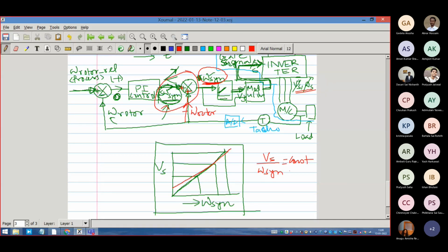So what will it do? It will integrate for more time, and it will take care of the rotor part also in the equation, in its integration part. It will take more time. Suppose it has started from 0, this output initially was 0, and it will integrate, and it will first read 400 RPM plus add 13.6 RPM. But when I know the system has to reach somewhere close to omega rotor speed, I help it by giving that as an additional adder part.